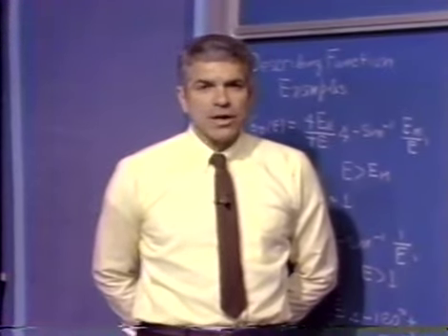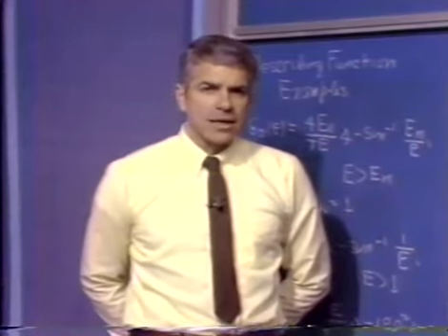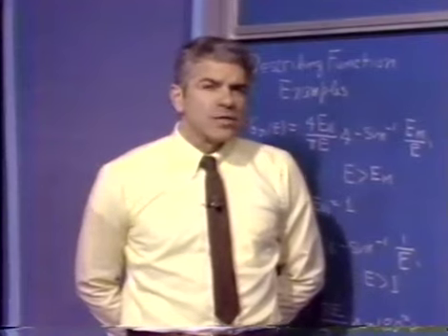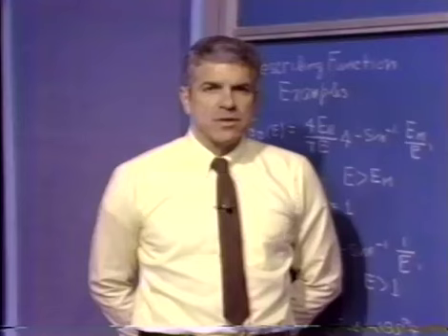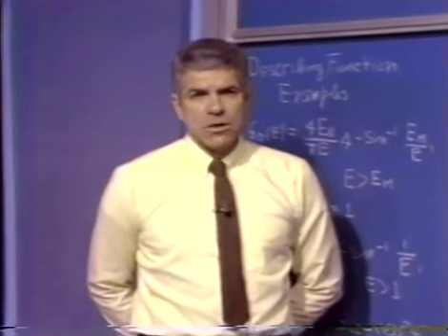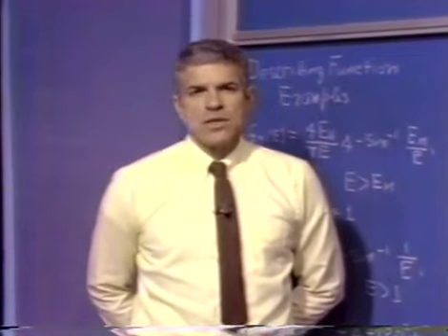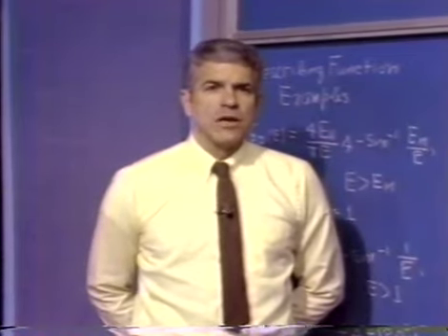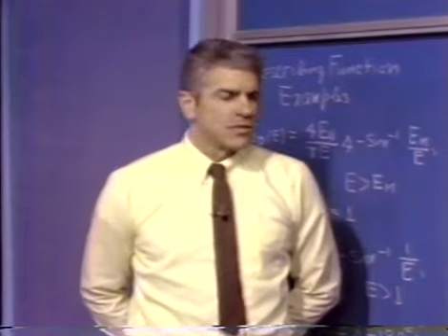We have a triangle wave rather than an approximate sinusoid at the input to the nonlinearity, and again, that leads to some errors. But in spite of the very large amount of harmonic distortion in this case, the linear elements are low pass, but only single order. We still get a reasonable approximation. If we didn't have a better way of solving this system, I think we'd probably be very happy to settle for 20% kinds of errors.